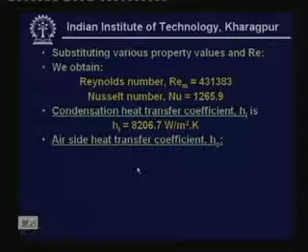Now let us find the air side heat transfer coefficient, because for calculating the overall heat transfer coefficient you require the heat transfer coefficient on the refrigerant side and on the air side. Remember that this is a finned plate fin type of condenser, so you have to use suitable correlations for plate fin type heat exchangers. If you remember, last time I mentioned that Kays and London have given several correlations for different types of condensers. So we will be using the general correlation suggested by Kays and London.